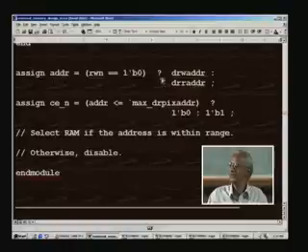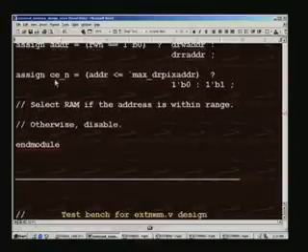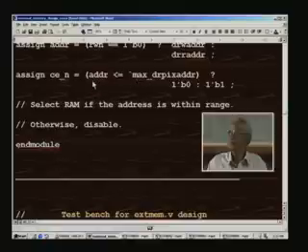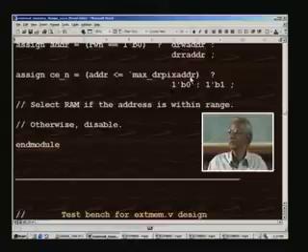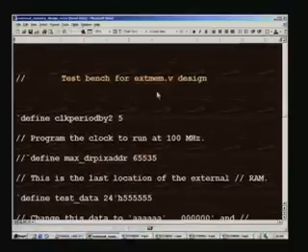So your address gets either write address or read address depending upon RWN, and you have also a CE generated here, although this is rather a dummy statement in this example, because we use only one single RAM. In dual case RAM, we can give a meaningful address and then select one of the two RAMs, and this is also a mux statement, and that is the end of the module here, and this completes the design for the external memory, and we will look into the test bench for the external memory.